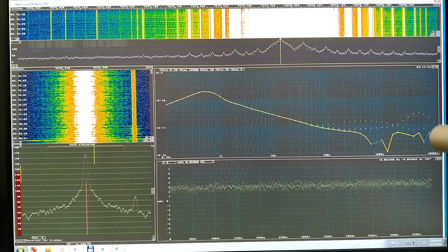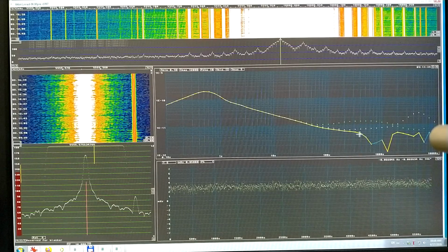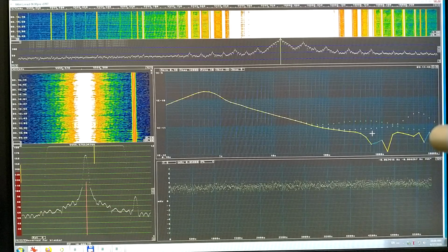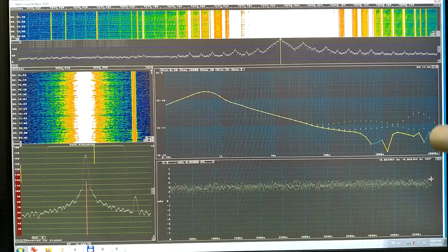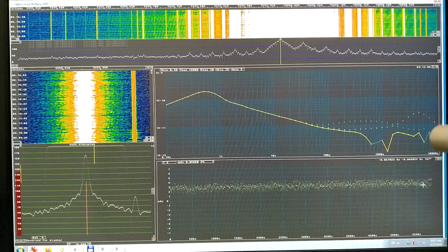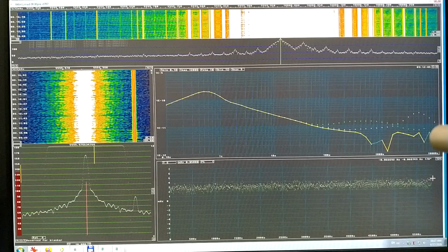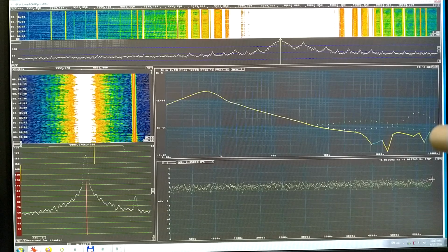This is 9 hours and 10 minutes, and what I see beyond 200 seconds or so is obviously unreliable. My oscillators are not good enough for that. One interesting thing is you can see here at the end of the time of the frequency versus time. When I enter the room, I stir up the air and the temperature changes on the oscillators and they drift apart now by about 1 millihertz.